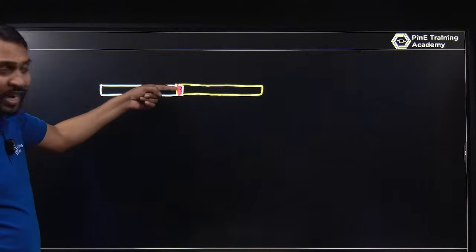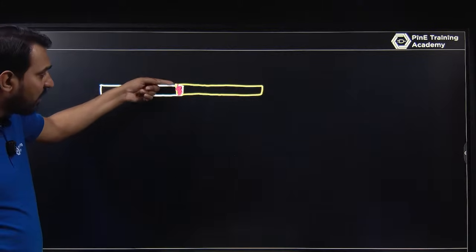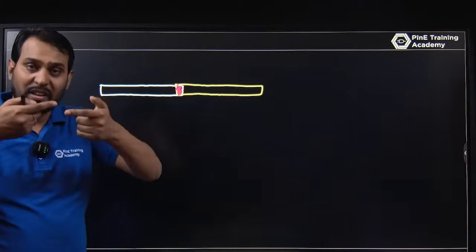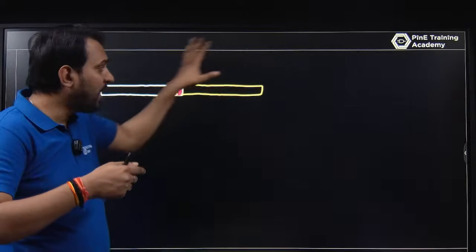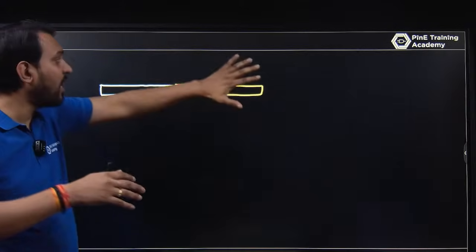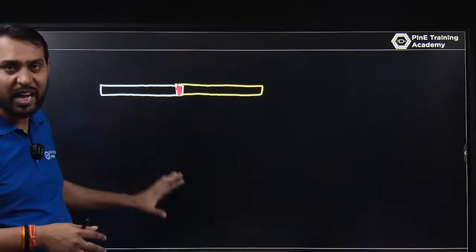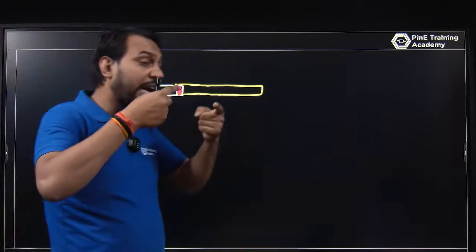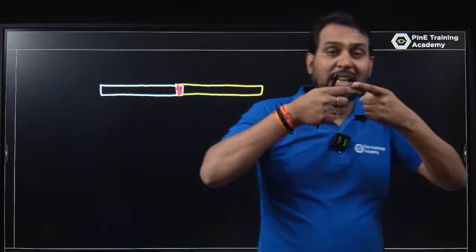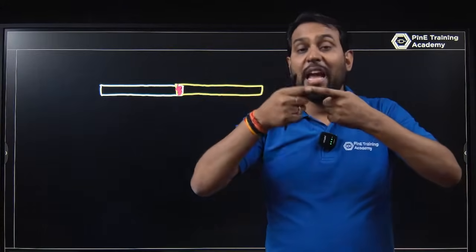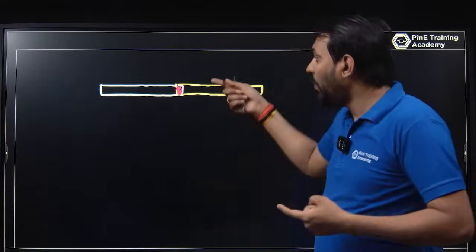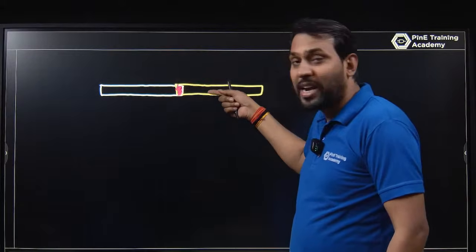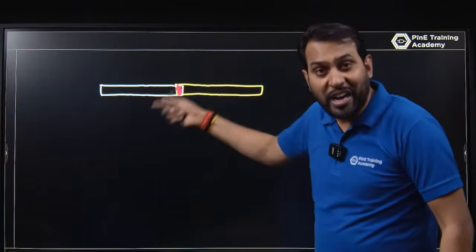If you are connecting with the junction, by the help of the junction you have two conductors, and in between that, in the silicon, let this be a black screen, this is silica, and on the silica you have a field oxide. If you are connecting two elements on a junction, that junction will behave like a capacitor. Why? Because you have two conductors and in between you have a field oxide.